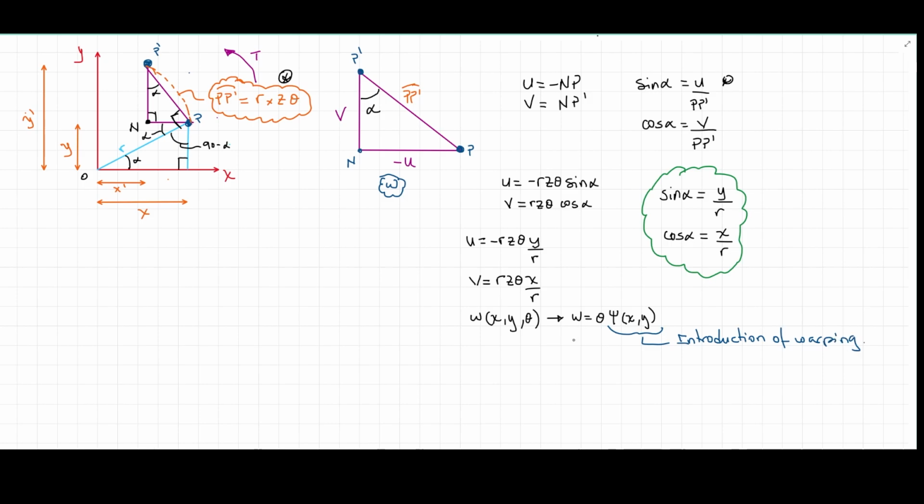Because we're talking about a displacement in the longitudinal axis, which we haven't considered before, but it's going to happen, and that's going to create certain irregularities. The beautiful thing about Saint-Venant is that it is a theory that allows us to separate what is torsion from what is warping. So we can treat them, not definitively, but as independent individual quantities to see the effects of each one of those, and that is something Saint-Venant allows us.